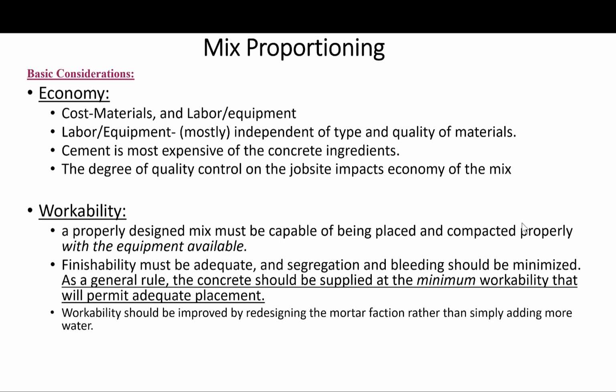I would overdesign to make sure I end up with the required properties. And as I have mentioned several times, a deaf ear should be turned to the frequent pleas from any job site for more water. Basically, we're talking here about small jobs. On bigger jobs, there is more quality control in place, and typically the use of admixtures will help eliminate the workability problem.